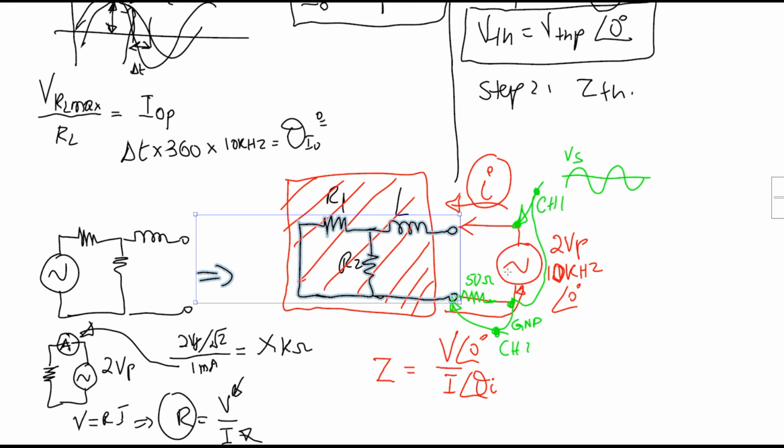If you are using Tektronix, the one we use, they have 4 channels. 2 channels are grounded. So if you ground channel 1, no need to ground channel number 2, the probe number 2. Otherwise, just to be sure, we ground both of them, and that's it. So this will be given by channel 1 here. Channel 2 will give another voltage across this resistor here.